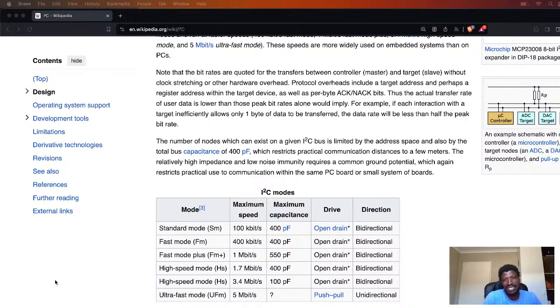So you had to do this dummy read, dummy send thing, which is kind of fixed in I2C with auto ACKing and auto NACKing. And we'll get to what ACKing and NACKing is, but basically at the end of each data packet, the slave will send an ACK, which is an acknowledge that we got the packet, or a NACK, which is we did not get the packet.